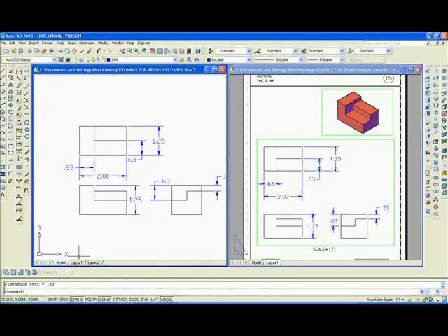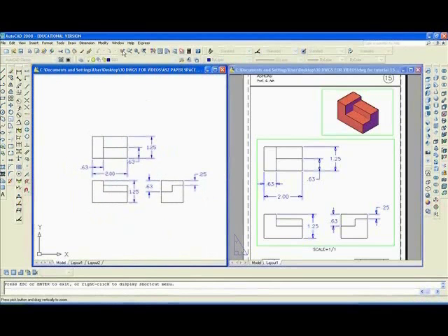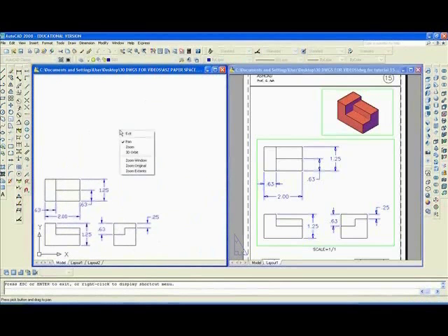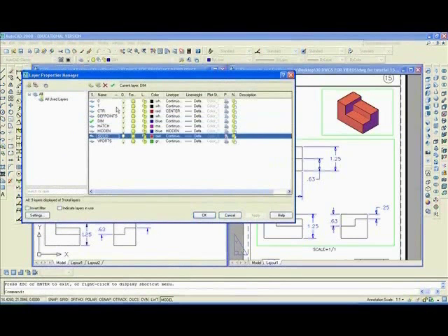And of course, as you know, if you take off ortho and you take off OSNAP, you'll be able to click on a dimension, and then locate it where you want it, and pick that point. So the drawing and the dimensions look adequate. So I'm going to scale it down, then pan over as usual, and we're going to make layout solid current.